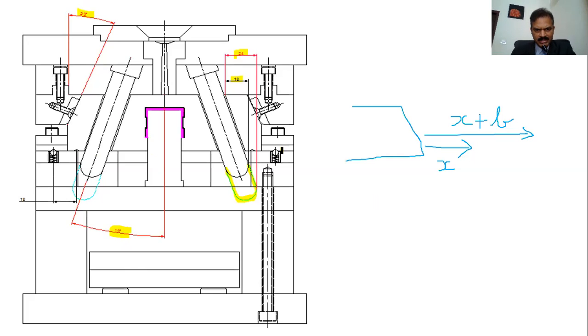And another thing which you have to pay attention to is this dimple here. The distance from here to the ball catch screw should be exactly the amount we have designed the finger cam, the movement of the slide. Clear?